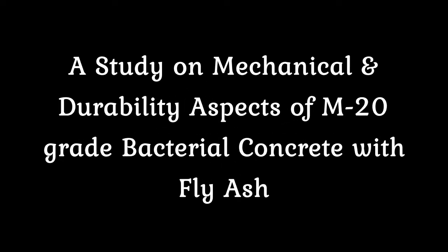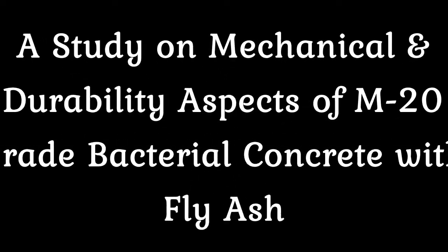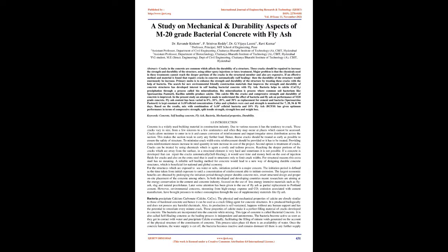A study on mechanical and durability aspects of M-20 grade bacterial concrete with fly ash. Abstract: Cracks in concrete are common, which affects the durability of a structure. These cracks should be repaired to increase the strength and durability of the structure, using either epoxy injections or latex treatment. The major problem is that the chemicals used in these treatments cannot reach the deeper portions of the cracks in the structural member and are also expensive.